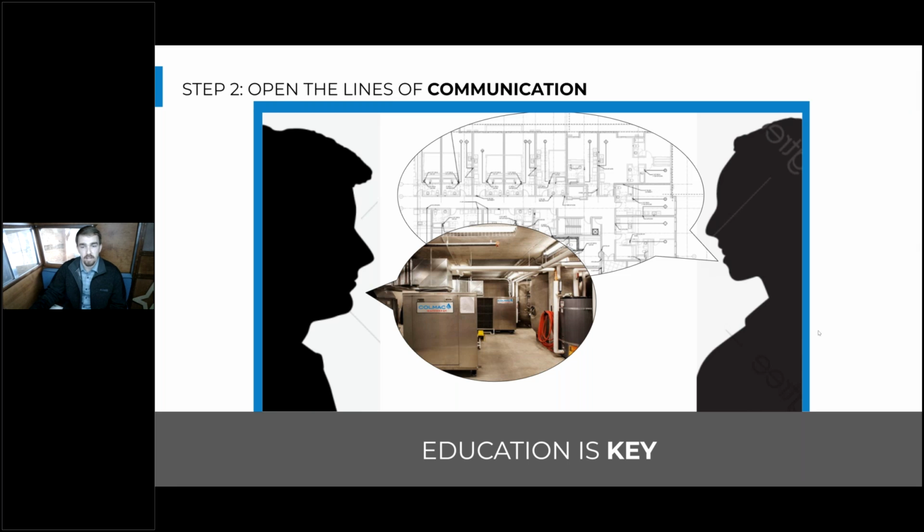And then on a project level, you'll need to make sure that you understand the engineer's reasoning behind why they've made the design the way they have, because you might be really familiar with boiler systems, but heat pump water heater systems are a lot different, and a lot of times there's good reason behind piping that would seem wrong in a lot of other cases. So having a call with the engineer to go over the design and making sure they answer any questions you have about it is really important.